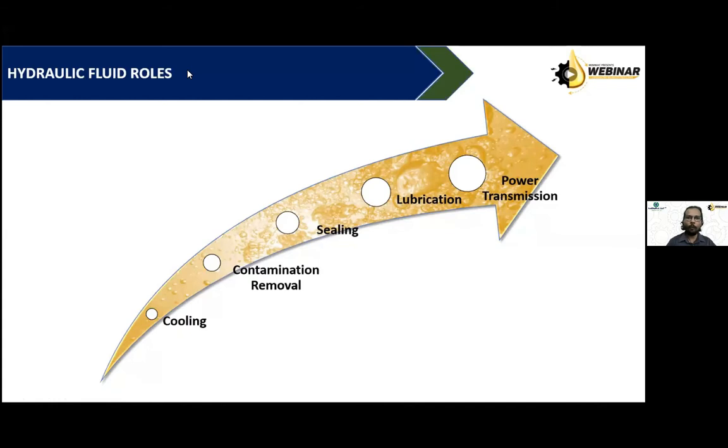Since it is operated by a solenoid coil, in due course of operation, it will get heated. The oil passing through this valve will take away the heat. Then any foreign particle sticking on the body or on the spool will get washed out by the hydraulic oil or fluid.